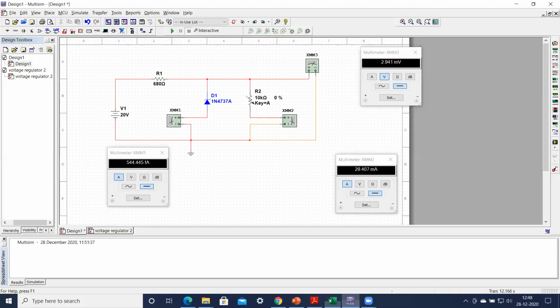So just go to your simulator, and if you make it 2%, you just click onto that, and on the keyboard you can press the right arrow. It will slide, and the increment will be by 2%, so the step size will be 2%. When it is at 2%, this value will equal 200 ohms. Now you can simulate this particular circuit.